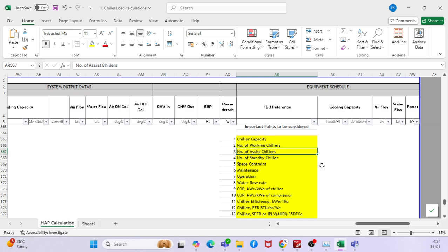When you talk about the chiller plant manager, it will calculate the runtime hours. Say for example, one chiller has run for 6 days. It will calculate that it has more running hours. It will calculate the running hours for all the chillers, and the one with more running hours will be switched off to cool down. That is a logic you write, right?